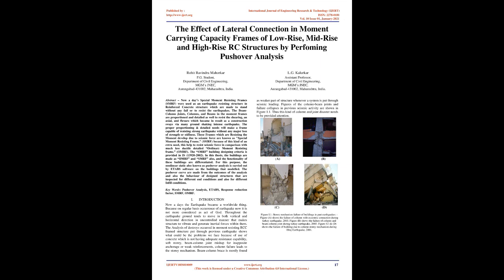buildings is compared. For this purpose, the nonlinear static analysis, also known as pushover analysis, is carried out by ETABS software on the modeled buildings. The pushover curves are made from the outcomes of the analysis, and the behavior of the designed structures is inspected for different end conditions and also for different infill conditions. Keywords: pushover analysis, ETABS, response reduction factor, SMRF, OMRF.